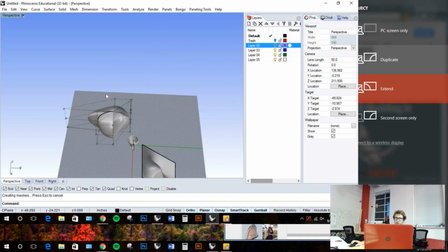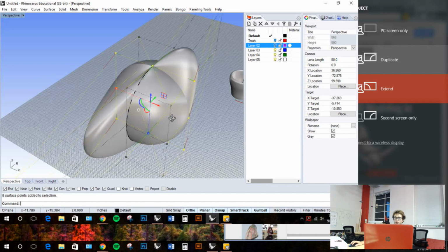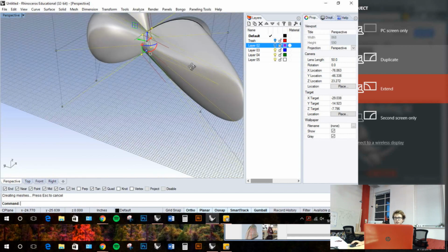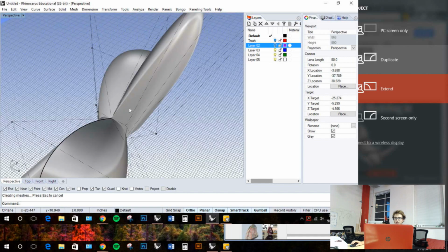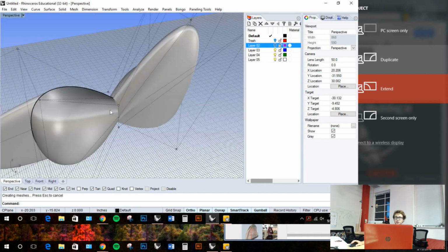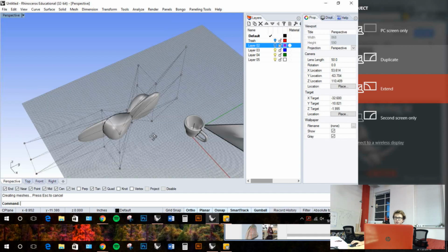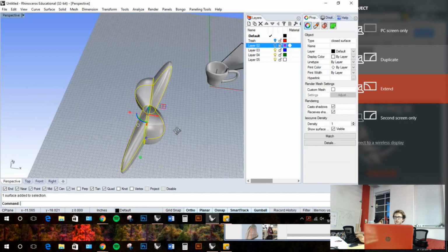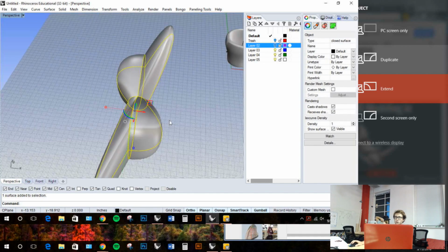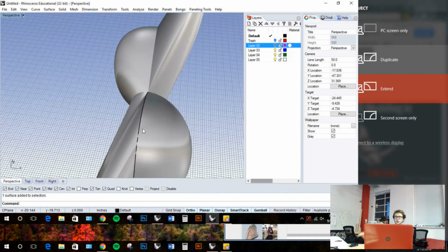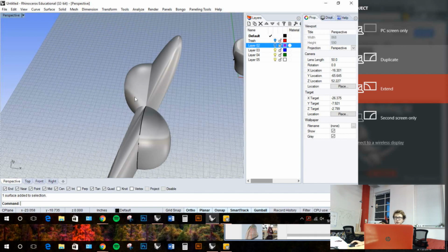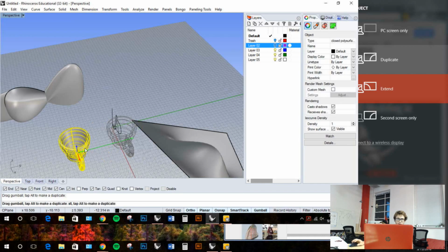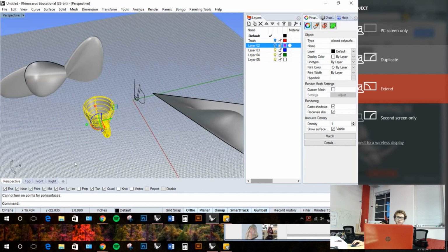You know, you can select control points and contract them as well. And we're ending up with something totally random, but it really allows you to play around as much as you want. The only problem is that points on is generally very easy to use for a surface, which this sphere began as. It was a closed surface, but say I have something like this mug. I can't turn points on for it. You can see here, cannot turn points on for poly surfaces.